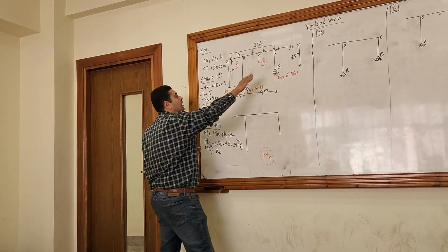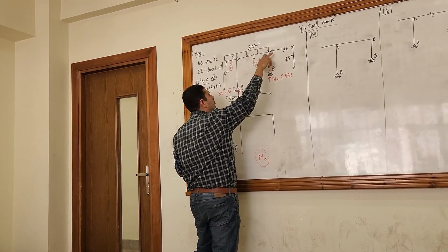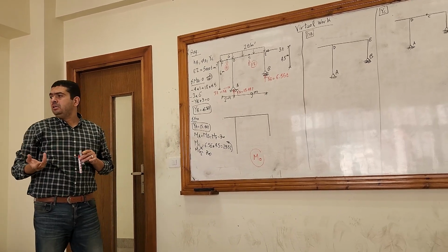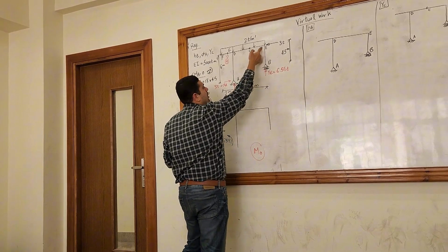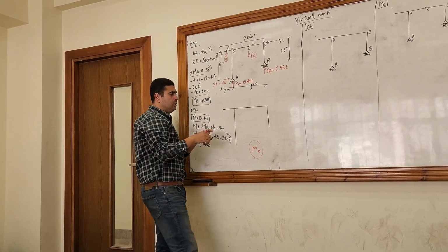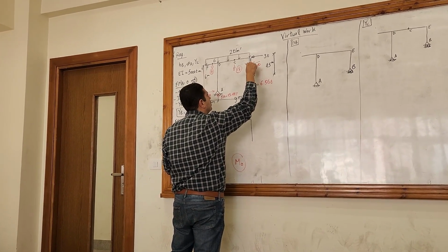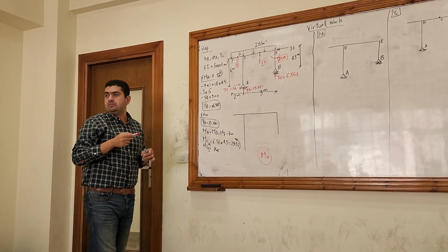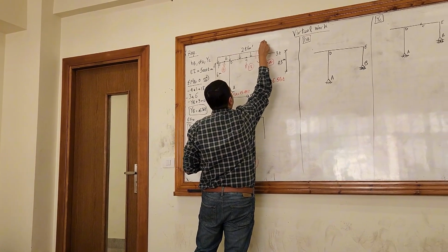Is there any forces at the part EB that gives a moment at E? There is only one force, which is YB 6.56, and it passes through E. Is there any other forces that give moment at E or around E? No. So the moment here is 0. So the moment at E from the other side has to be equal to 0.